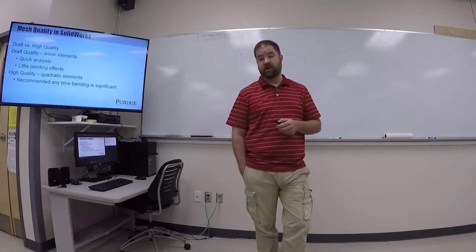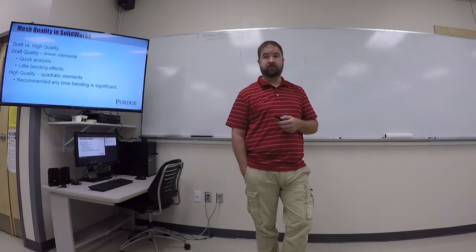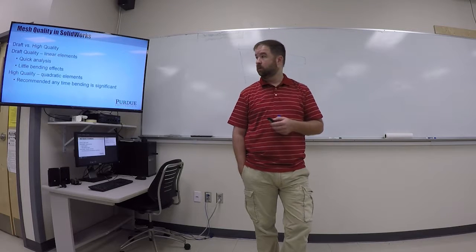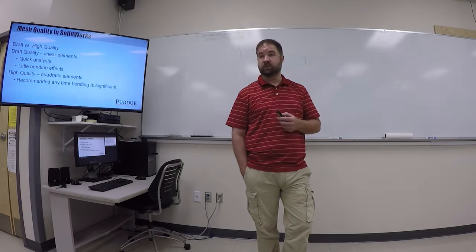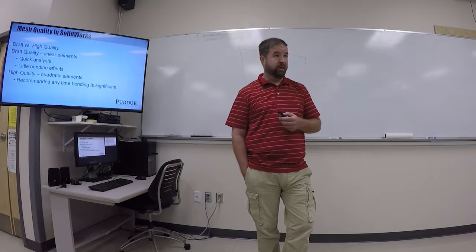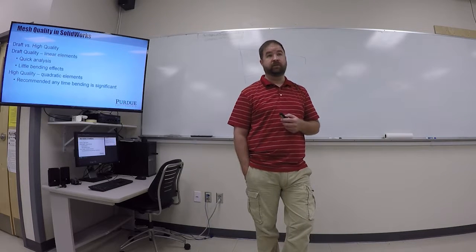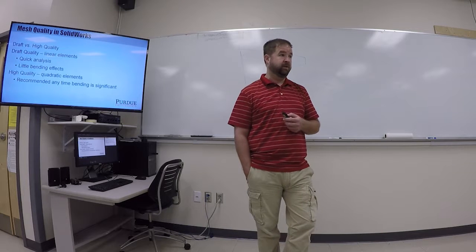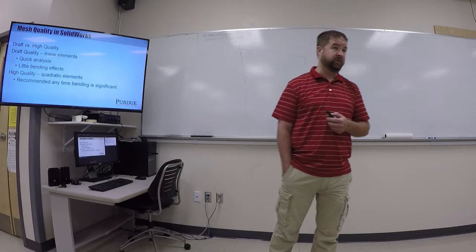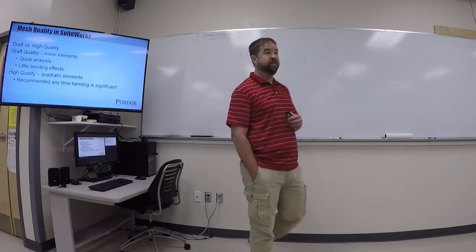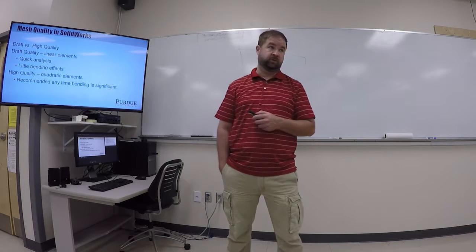For our assignments, we're talking minutes at the most for most of these analyses. The time problem doesn't really become an issue. But like I said, when I used to work in industry, it was not unusual to have a computer crunching away for hours on a model. And that's really, really frustrating to sit there and wait a couple hours for it to spit out an answer and then discover you didn't put the constraints in correctly or something like that. So the purpose of having the draft quality is to speed it up so that you can get a quick result. And then once you're happy with the way it's modeled and you want a better result, then you can run it again with the high quality mesh.